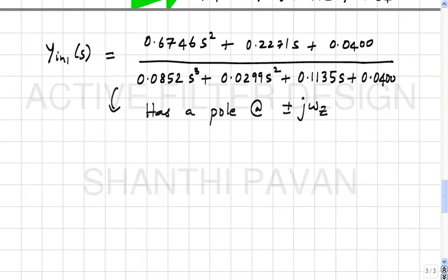And just like in the all pole LC ladder case, the admittance pole was coming because of the capacitance in shunt. That was the frequency at which the capacitor admittance was going to infinity, right? Now here also the reactance goes to infinity, but at a finite frequency plus minus j omega z. So the conclusion is that Yn1 of s has poles at plus minus j omega z, and those poles must be coming from the shunt arm, which is the series LC network, correct?